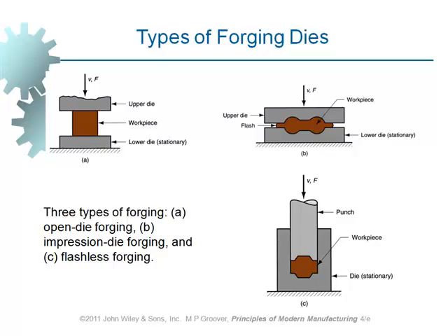And forging can also take place at lower than recrystallization temperature. If this is the case, still we are improving the properties of the materials. Properties such as strength and also hardness increase when material is squeezed by making use of forging process. Cold forging is also of common use, but of course, hot forging is more common than cold forging. Okay? Does this answer your question? Okay, good.